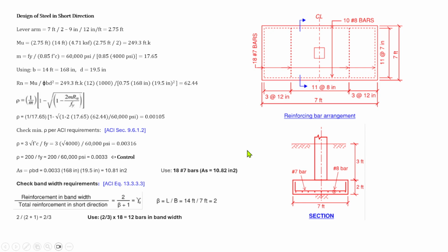So here, take note, guys, that the most common problem on the site is the arrangement of the reinforcement. We have to take note that the main reinforcement here is always below the transverse reinforcement, because that is our main reinforcement, which is this one here. But sometimes they reverse this one. Instead of putting it down, they put it above, which is not correct. So that is the common mistake on the site.